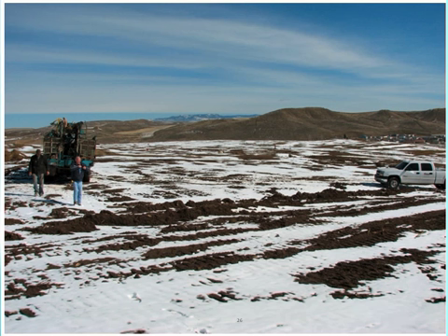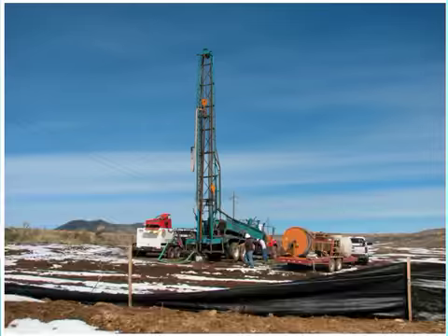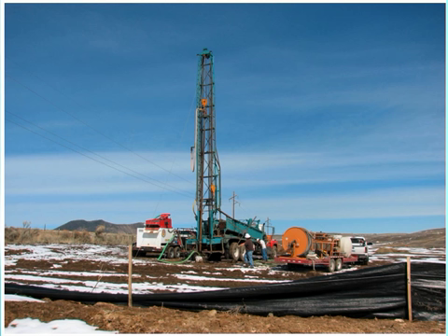So what does this test look like? Well, the first thing you're going to do is hire a contractor to come out on site, and he's going to figure out where this test hole is going to go, or you're going to help him figure out where this test borehole is going to go. Once you figure that out, he's going to set his little rig up here, and he's going to drill that test hole to the specified depth. Now, it's key to know that whatever depth you specify for this TC test is generally going to have to carry through the duration of the project.